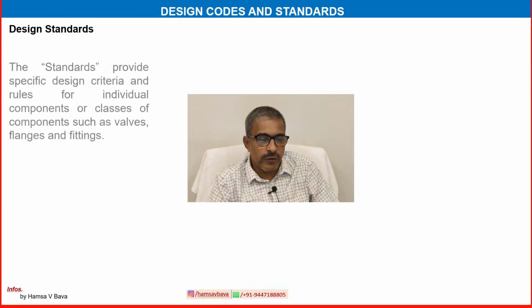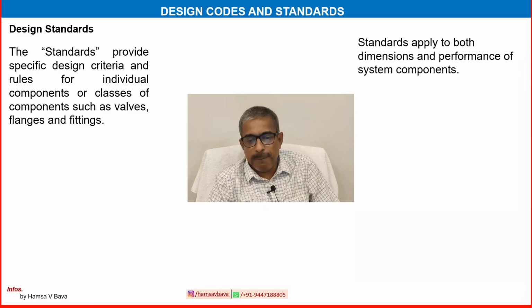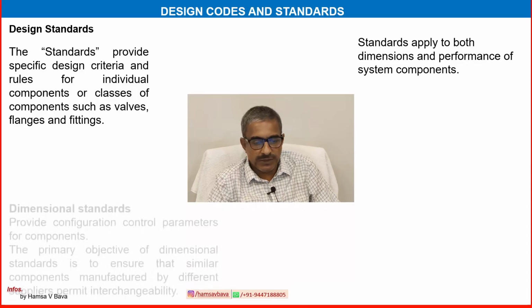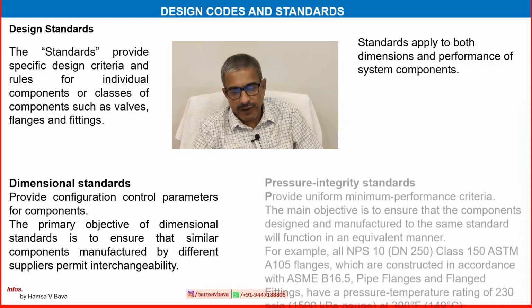Design standards, let us look at that one. The standards provide specific design criteria and rules for individual components or classes of components such as valves, flanges and fittings. Standards apply to both the dimensions and performance of system components. Dimensional standards provide configuration control parameters for components. The primary objective of dimensional standards is to ensure that similar components manufactured by different suppliers permit interchangeability.